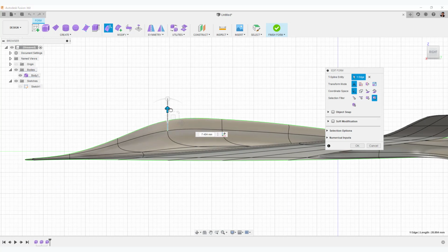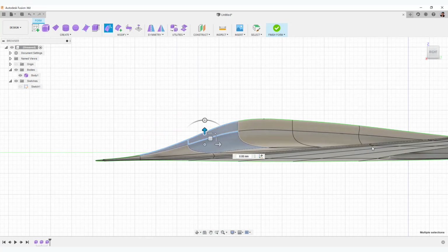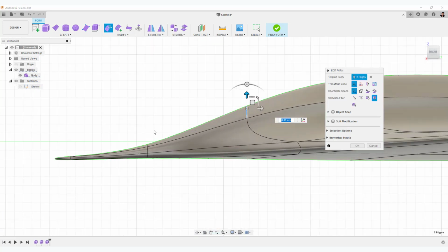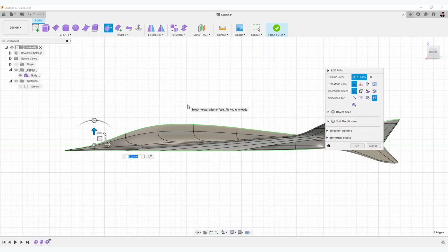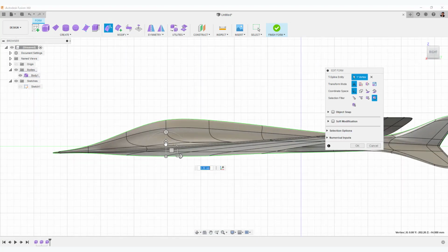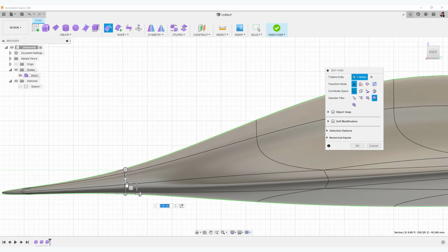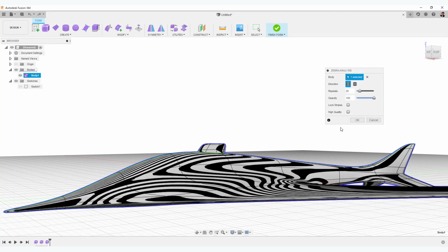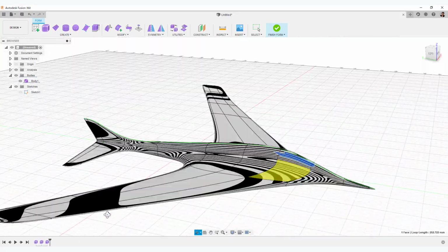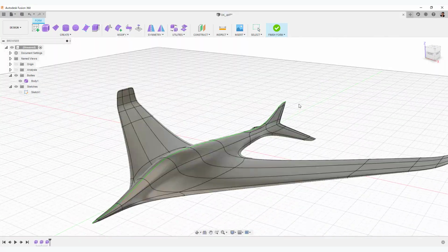It's finally the last phase. Make the final tuning while checking the whole thing. When modeling is finished, make sure to use Make Uniform to optimize tension. Check for weird things and zebra highlights and the form modeling is over. Select Finish Form in the toolbar to navigate to solid modeling.